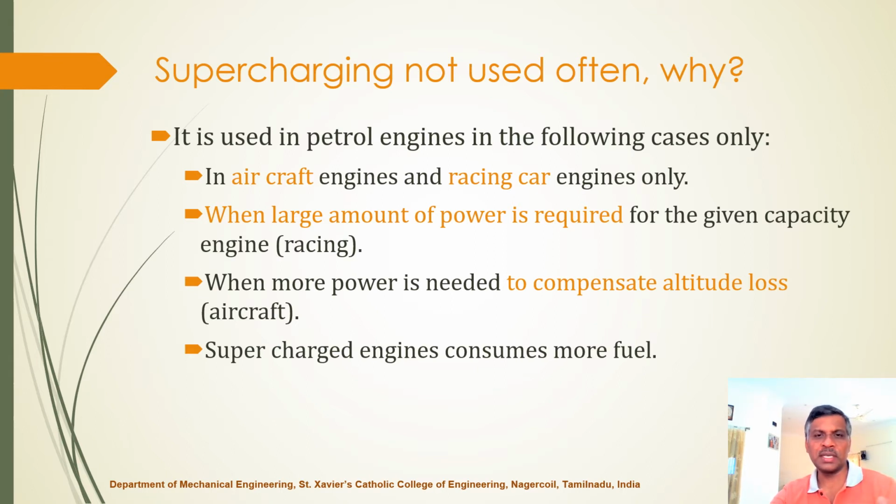So supercharging is meant for racing cars, aircrafts, especially warplanes, and if you need more power for the given capacity, the capacity is very important here. So for example, race bikes, they say 500 cc, 500 cubic centimeters is the cylinder volume fixed. So how can you get more power from a 500 cc engine? That is the question. Then you can go for supercharging, not for ordinary cases. That is why it is not quite often used.